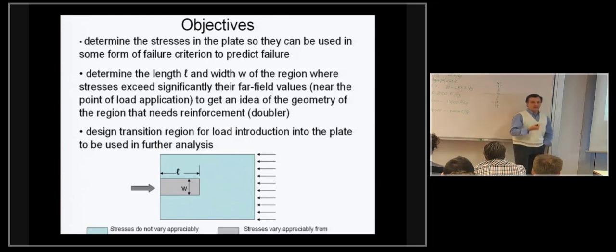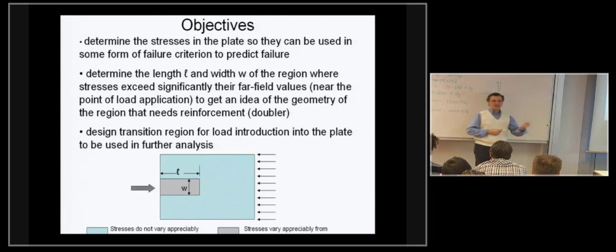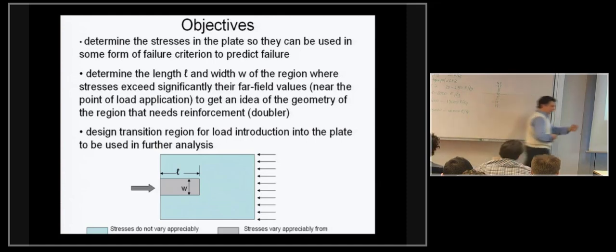So the challenge becomes to determine over which region from the load introduction here, the concentrated load, over which region measured by a length L and width W, will the stresses coming from this concentrated load be much higher than the far field stresses, and therefore would define the region that we would need to reinforce. So this is actually now becoming useful